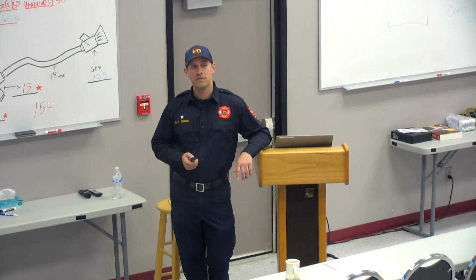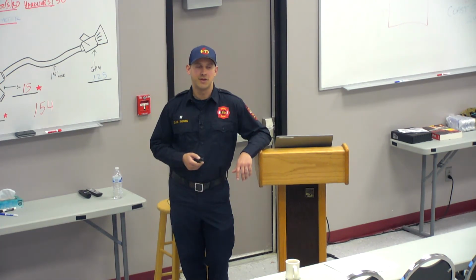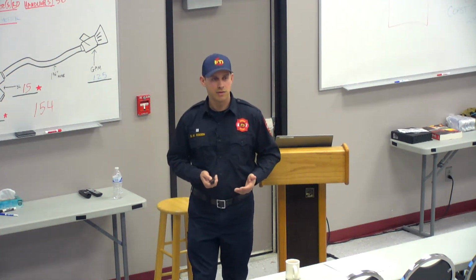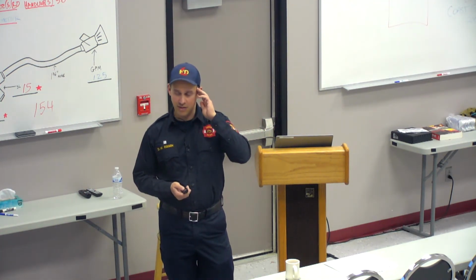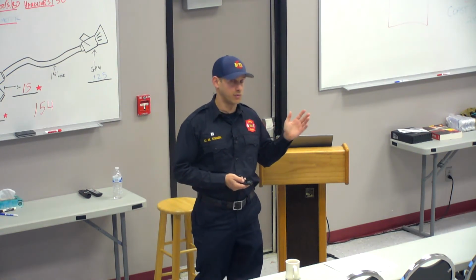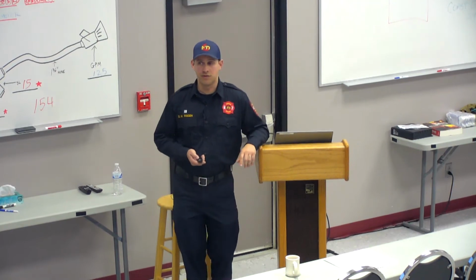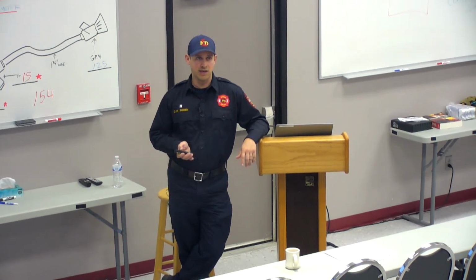All right? Have we all heard on the compound intake gauge, don't go below 20? Yes, sir. I'm going to contradict a lot of people, but why is that? You're trying to prevent cavitation. Cavitation of your pumps? Is that what everybody's heard? Yes. I've heard that. I'm not saying it's wrong. I think based off the things I've read and people I've talked to even within our own department, that's not the biggest fear of going below 20. You'd have to get really close to that 0 number, and we're never going to get in the negative unless we're drafting, before you start cavitating the pump.